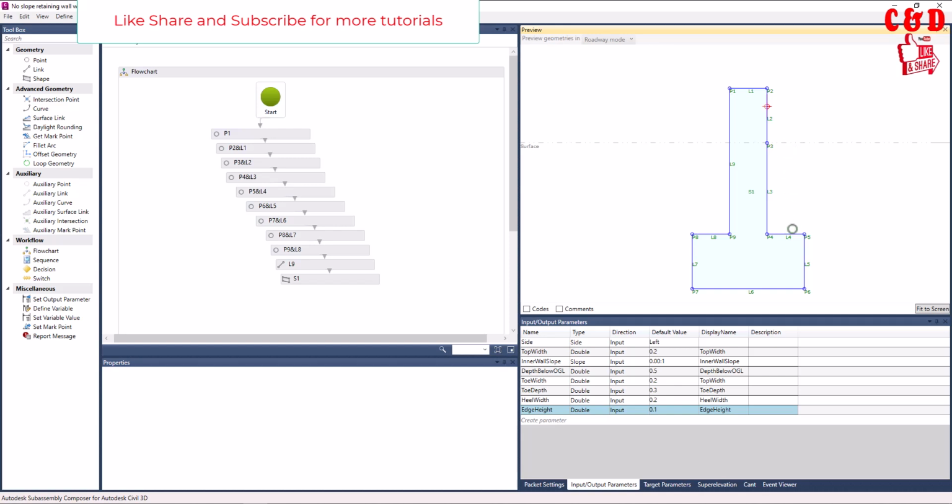Another thing is, in this kind of retaining wall, normally this particular part, toe and heel, are almost the same, but you can keep them variable. Sometimes you have backfill over this part, so this part can be larger while another part can be shorter. So you can define these two as toe and heel widths. Another thing is the depth of the retaining wall. These are the parameters that need to be defined.